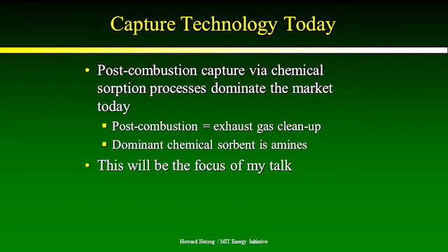Next slide, please. So as I said, the bulk of the processes are dilute or very dilute, and the main process for capturing today is post-combustion capture using chemical sorption. Sometimes people call it chemical scrubbing. The process that dominates the market uses amines as a sorbent. When I say post-combustion, we just heard about it, but basically it's exhaust gas cleanup, looking at what's coming out of the tailpipe. And this will be the focus of the next several slides.